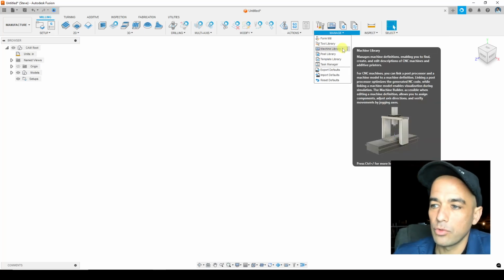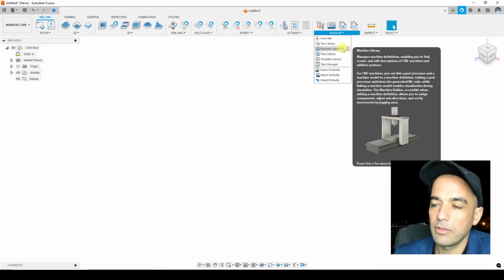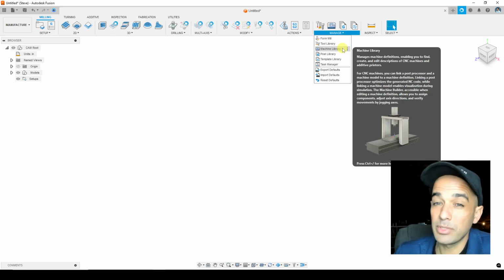There's also the potential for a machine library. You can have a 3D model of your CNC machine that moves as your machine would move during machining. This is a bit more advanced, but we will get to this, and for some of the programs, we will have our machine in there. It's not necessary, but it does add another visual verification layer, and it's particularly important if you're doing multi-axis work, because there are so many more potential collisions between all the other new moving parts of the machine.